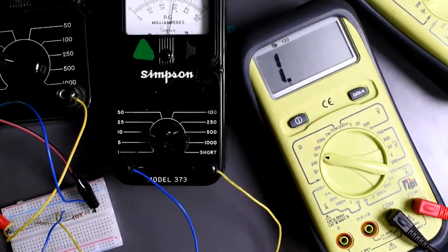This reading here is 0 ohms. If you see that 0, please do not say that it measures nothing. When it comes to this, I say to my students, nothing is not a word in the dictionary right now. Just forget about the word nothing. It's 0 ohms when you join this, so there is no resistance. 0 ohms means that there is no resistance between those two points. It's not nothing. It's a continuity, clear continuity. Closed circuit, closed pathway, 0 ohms, no resistance, but it is not nothing.